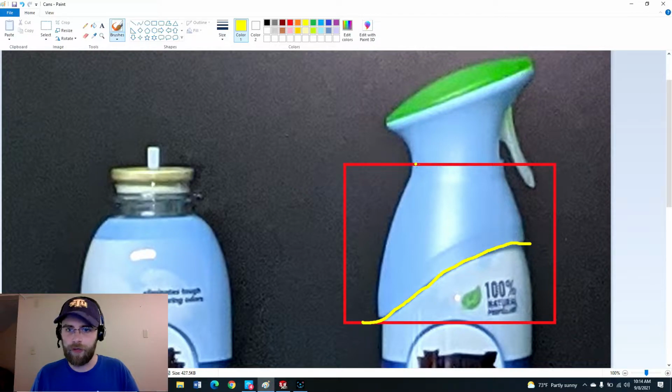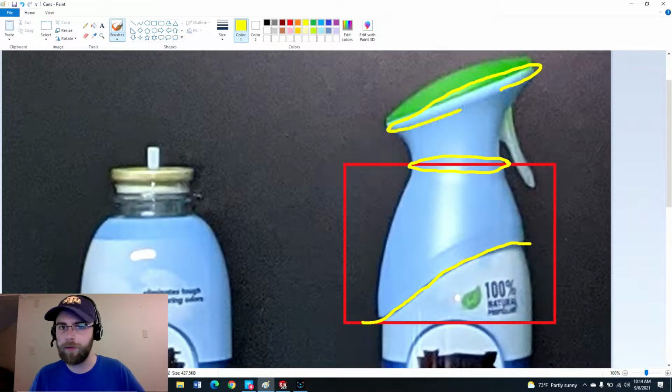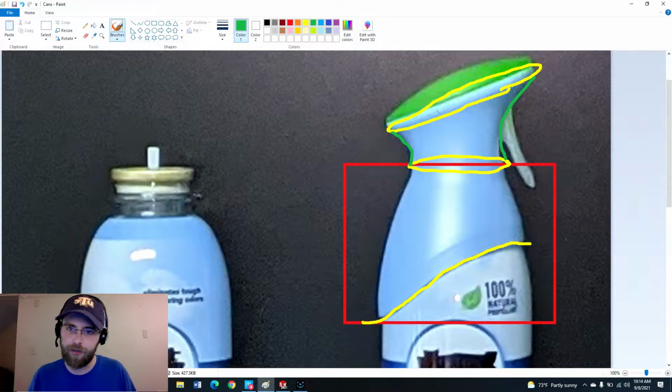So the bottom half of this is really just a revolve and then cutting away that curvature. And then from that parting line up, I see a lofted feature where it's lofting from this circle to an oval. And then we'll use some guide curves to get from that circle shape to that oval shape. And while I was running through this beforehand, I realized that there were a couple of extrudes, a couple of planes we'll have to deal with to directly match up the way they have the top of this, but it won't be a big deal.